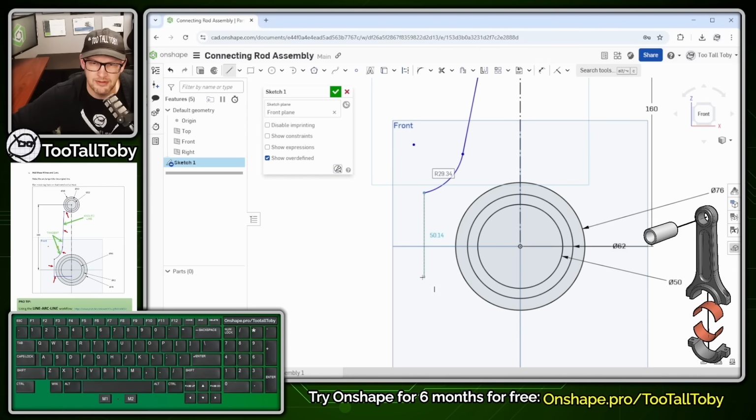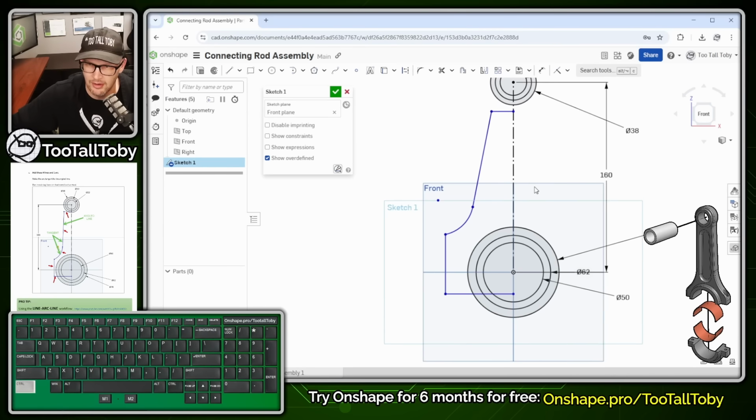So that is a very useful shortcut workflow in Onshape, the line arc line workflow. So now we'll finish off this sketch by making a vertical line here, and then we're going to move over here and make a horizontal line, which is vertical to that orange point. So once again, we're getting that orange highlighting. So we single click, and there we go. We can hit escape. That gives us those 4 lines and that 1 arc.